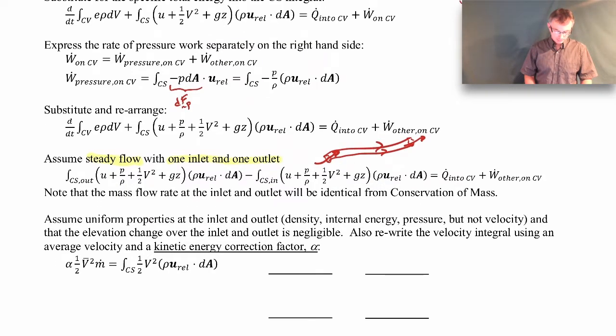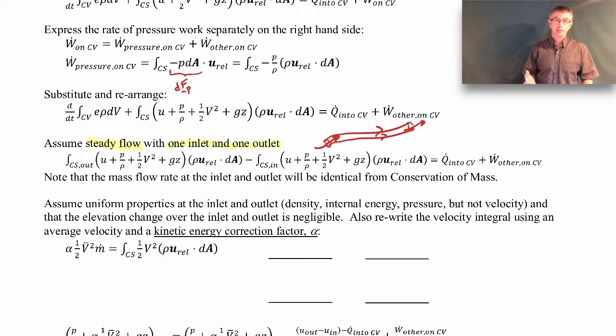As far as the velocity, that one I do have to worry about, because we know from the Navier-Stokes equation solutions that the velocity profile in a pipe is not uniform. It actually has a profile to it, right? So a real velocity profile, let's say it's laminar, looks like that. There's the no-slip boundary condition at the walls, and it's maximum at the center.